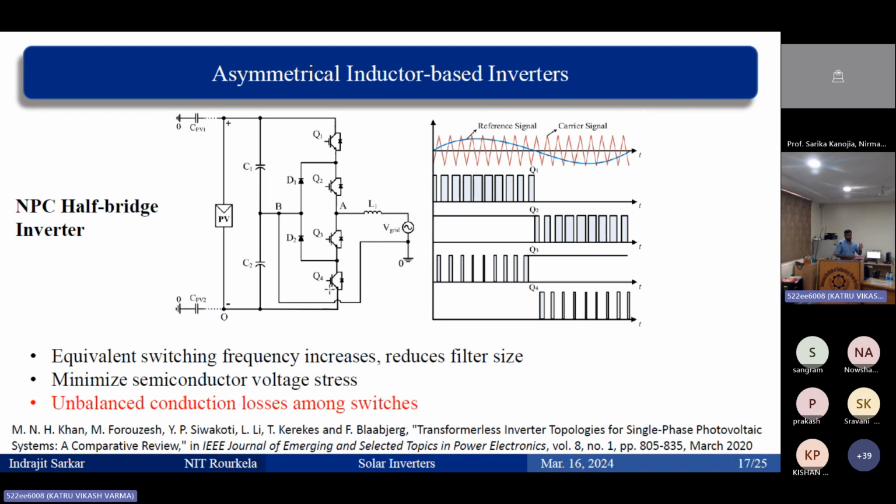Now the problem is always this, keep in mind when you are working in power electronic systems. People say that yes, we have reduced the number of switches. Somebody is using 10, I am using 9. Somebody is using 8. It will never happen. If somebody is saying that, okay, I have reduced the number of switches, definitely the volt ampere of the switch has increased.